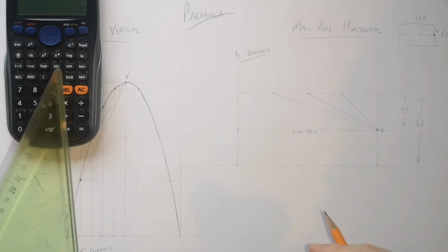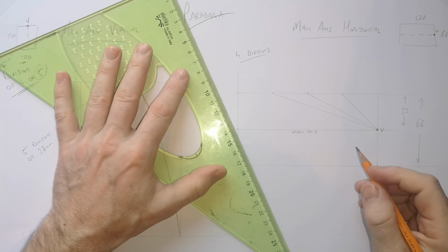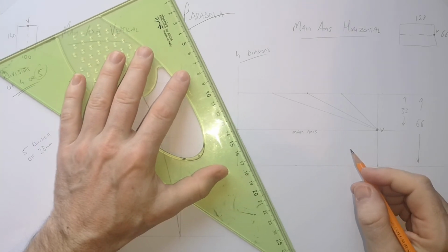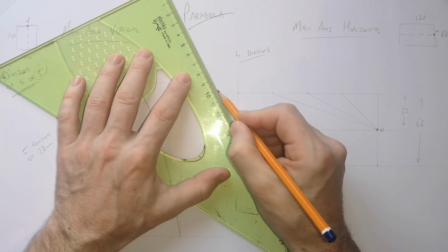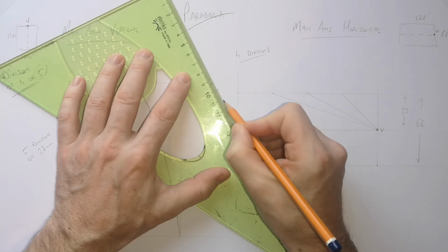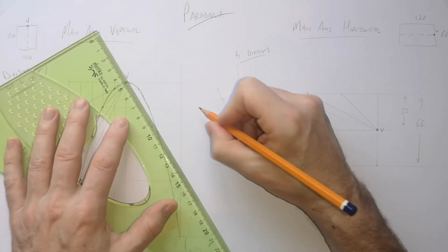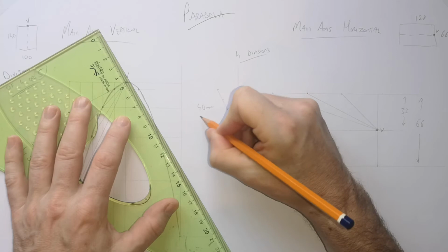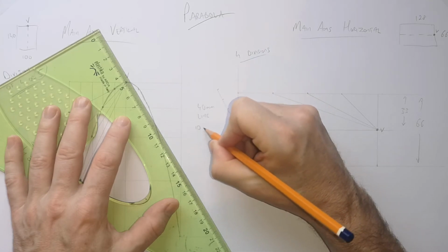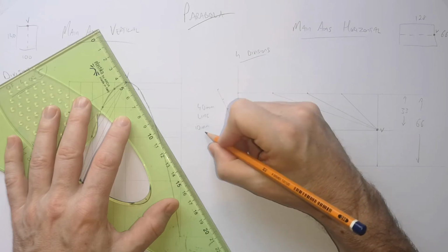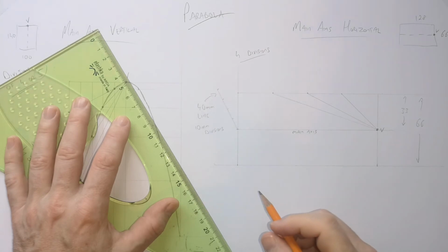Well, here we need to use a little technique to break it up evenly. So what we're going to do is go into 4 divisions. With my ruler here, I'm going to pick a number that's close to 33, like 40. And that divides very evenly into 4 in little 10mm slots. So that's a 40mm line with 10mm divisions. That's what we have here.